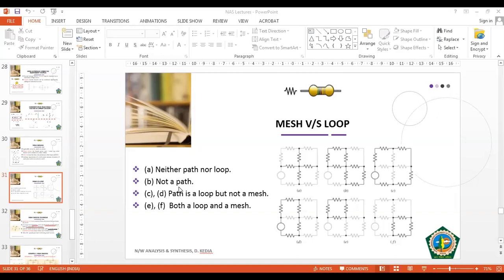Yeah, Sagar, unmute yourself. Sir, power will be delivered, then voltage will rise. No, sorry, power. See, there are two things. Power delivery means that whichever element is capable will deliver power. Okay, means you can say the current will be coming out of a source if it is able to deliver power. Okay sir. And if current is coming inside the source, from the positive terminal, then we say that power is absorbed by the source. Is it clear?